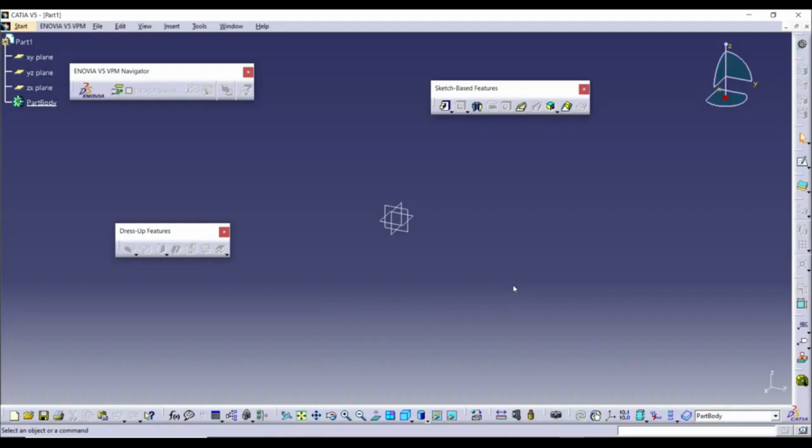Now we're going to show tools shaft and groove. Here we have tool shaft, and here we have a tool groove. With the shaft tool, we can take a two-dimensional profile and revolve it about a center line to create a 3D geometry. And with the groove tool, we can remove material from the geometry by revolving a sketch about an axis. So let's show how this works.